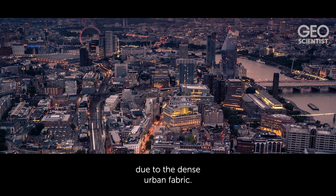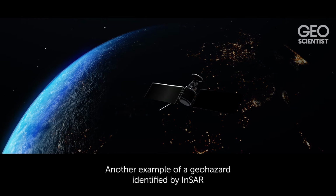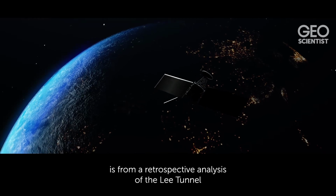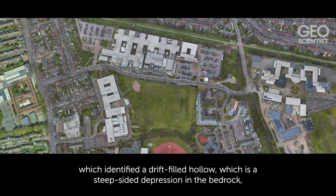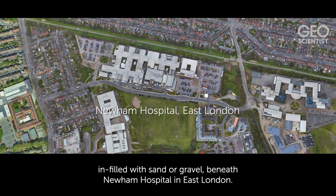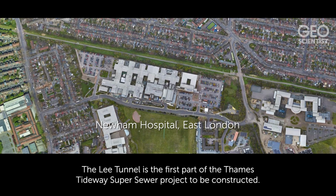Another example of a geohazard identified by InSAR is from a retrospective analysis of the Lee Tunnel, which identified a drift-filled hollow, which is a steep-sided depression in the bedrock, infilled with sand or gravel, beneath Newham Hospital in East London. The Lee Tunnel is the first part of the Thames Tideway Super Sewer project to be constructed.